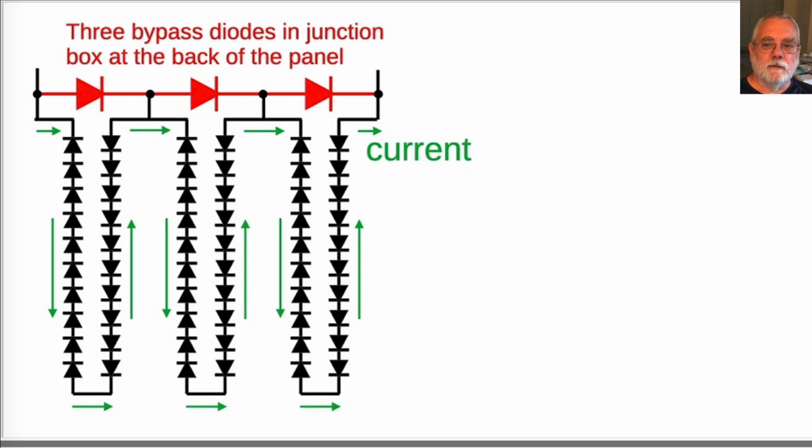The bypass diodes have higher breakdown voltage than the solar cell string sourced voltage, so they are just off in this normal operation. When forward biased, the bypass diodes can handle the rated current of the solar panel, so 10.6 amps for my example. The bypass diode should be reliable for the 30-year life of the solar panel.